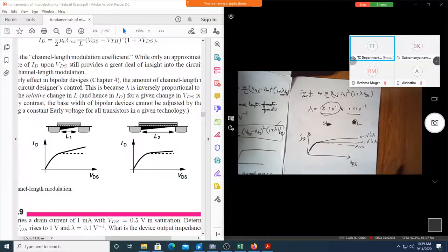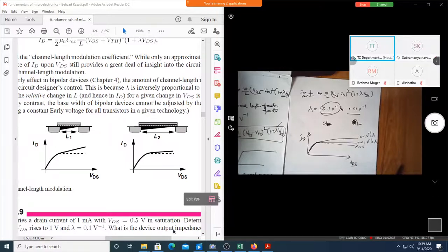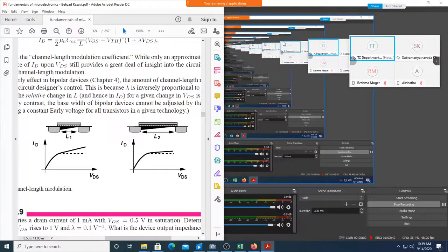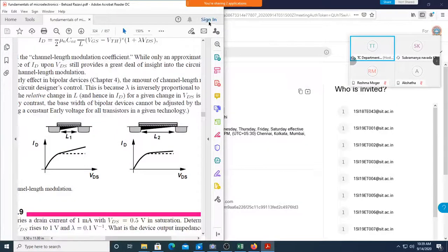Done? Let us see the impact of that in LTspice. Sir, how is this lambda value calculated? Lambda values will be given by the foundry people, when they manufacture the transistors. It is a parameter that is measured and given to us.